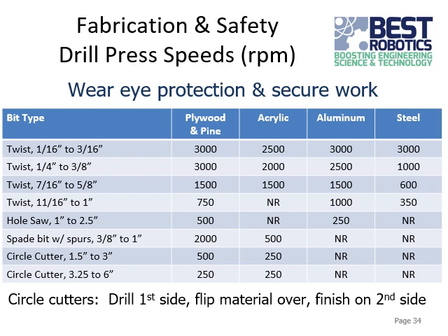The other thing here that's not really mentioned is that with some metals, at least with the harder metals like steel, you're going to want to use some sort of cutting fluid. That's basically a little lubricant that will keep the drill bit cool and keep it from overheating and deforming. With aluminum, you can get away with not using it because it's pretty soft, but a lot of times it's a good idea to use it anyway because it'll make your drill bits last longer.